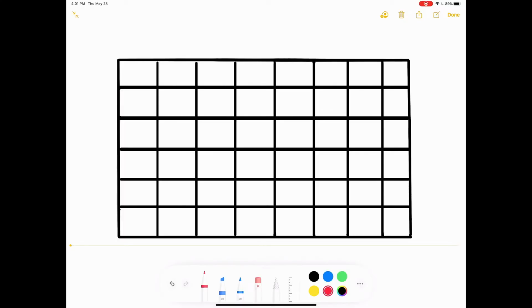Now imagine this grid. This is your sensor. Every one of these rectangles is a pixel. We have a default Bayer pattern of RGGB. What does that mean? Red pixel here, double green pixel here, and blue pixel here. Now this is a 2x2, therefore it's a quadlet, meaning 4 pixels.